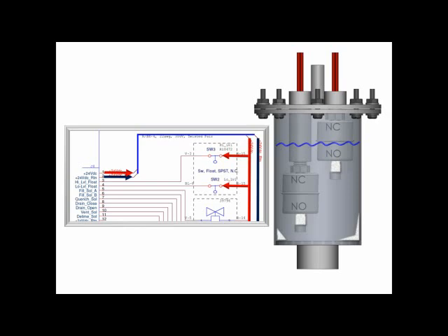The purpose of the high limit is to disable the boiler pilot, which ends the main burner flame if overheating occurs. A cause for this issue is frequently lime scale. As seen here in the float canister, the scale prevents the floats from closing and sending voltage to the relay board. If the low float does not report a low water condition, the boiler heat enable is not stopped by the logic board because the low water signal is not present.